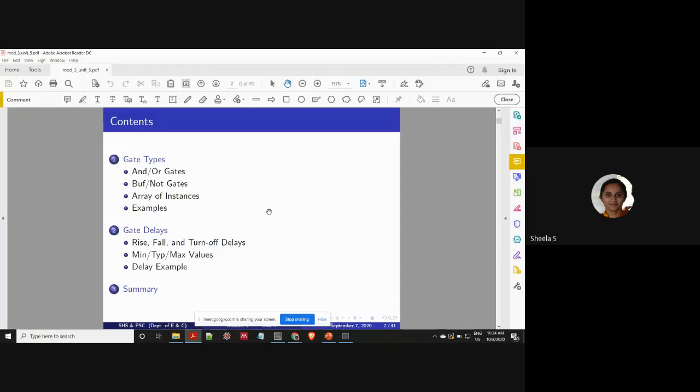There will be delay to read the input, delay to process the given data, and then delay to get the output assigned to the output pin. The delay may be in terms of nanoseconds or microseconds, which we may not notice. But still, every practical gate will have its own delay.